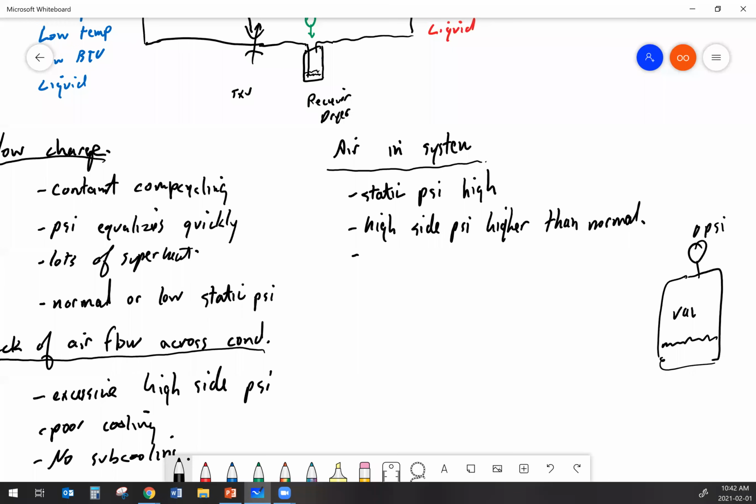That means it's actually in a vacuum. And if you have any leaks in your AC system, that vacuum is going to start pulling air into the system. So you've got a problem that happens over the winter, but you don't know it happened until you try to use that AC system in the spring.